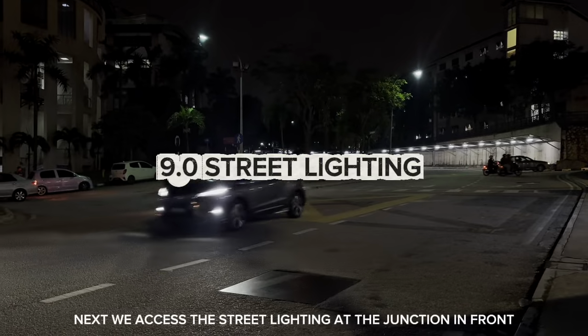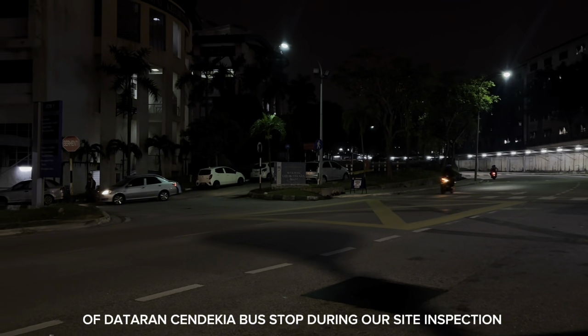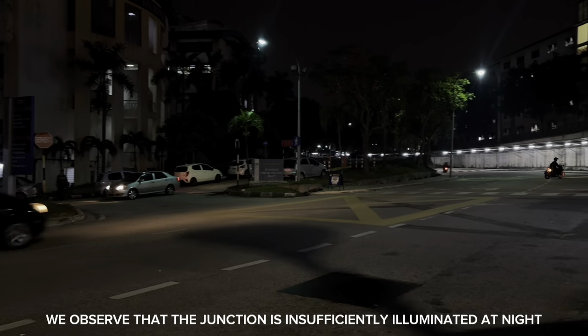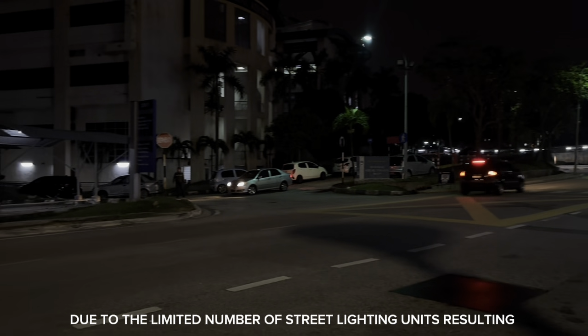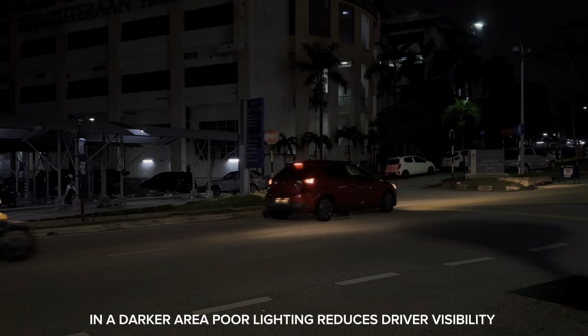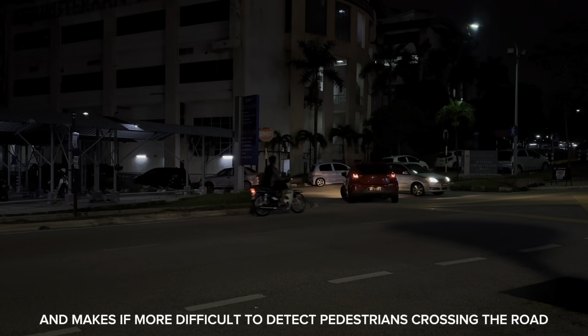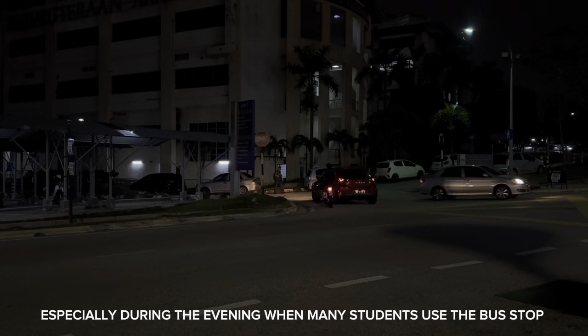Next, we assess the street lighting at the junction in front of Dataran Cendekia bus stop. During our site inspection, we observed that the junction is insufficiently illuminated at night due to the limited number of street lighting units, resulting in a darker area. Poor lighting reduces drivers' visibility and makes it more difficult to detect pedestrians crossing the road, especially during the evening when many students use the bus stop.